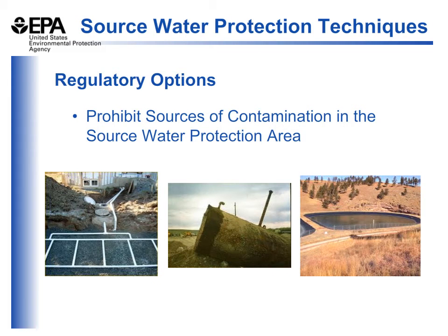What types of controls can we implement? We can have a series of prohibitions saying that land uses within this area cannot be built that may impact the quality of water that's being pumped by our drinking water supply. We can say that there can be no wastewater treatment plants within the wellhead protection area, or no industrial discharges of chemicals, or underground storage tanks associated with gas stations or home heating oil distributors.